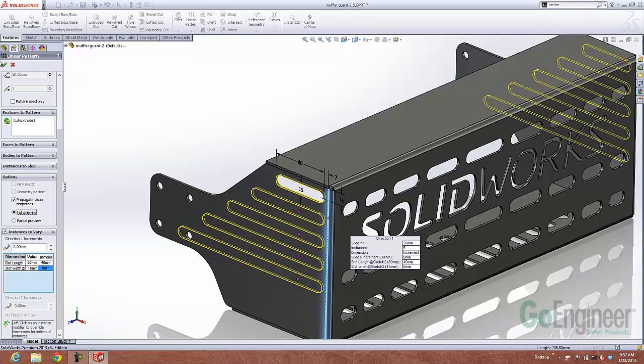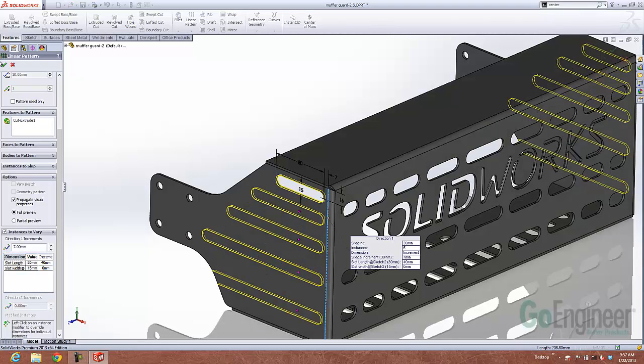And as it scrolls down, I do want to change the spacing in between them. Now, just a few minutes ago, I typed in 30 there, and that changed that overall 30 to 7. I made a mistake, and I should have clicked in here and said that was 7 millimeters. That will increase it. And you can see it's increasing here, but I have an issue with this particular guy. He's a little bit too tall. So I can actually come down here and select this little dot and say I can skip or modify the instance.